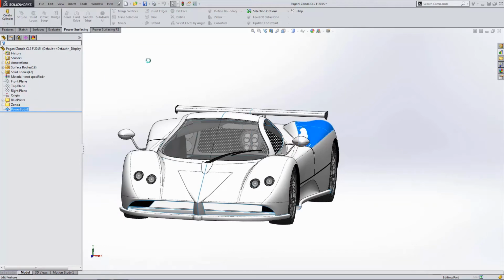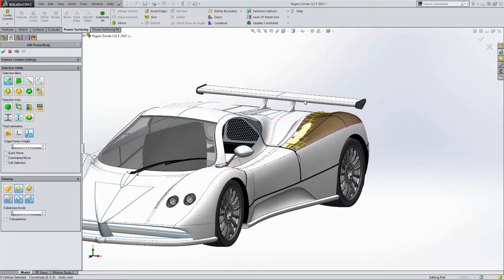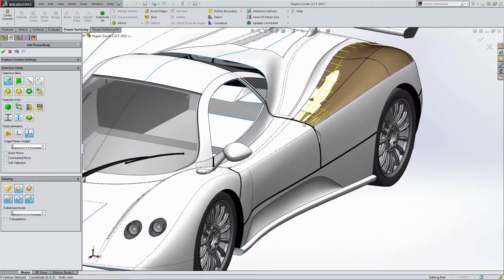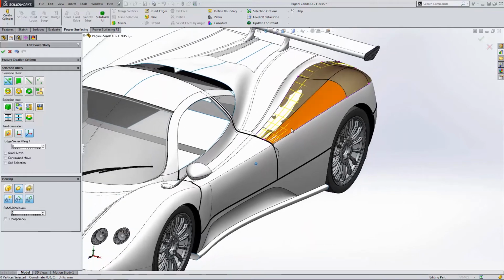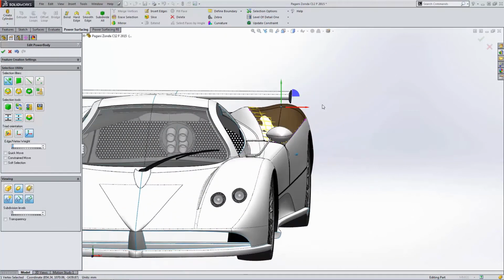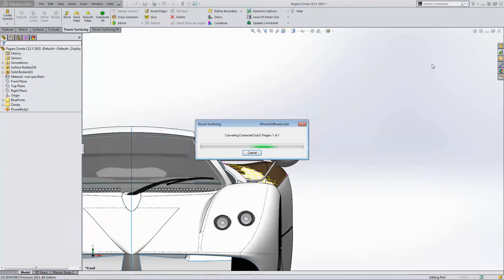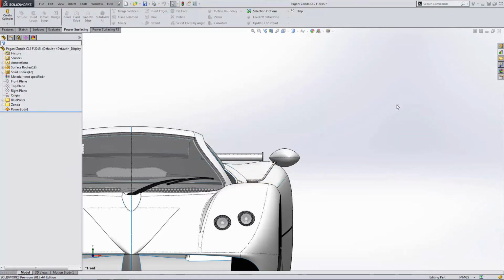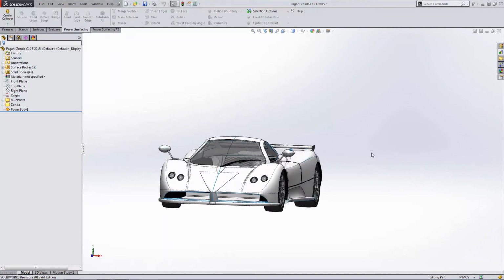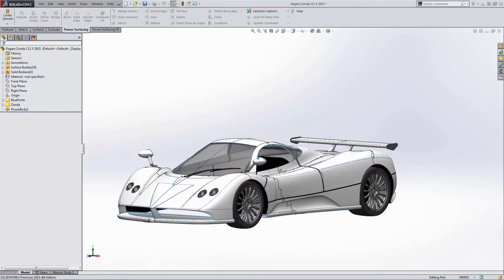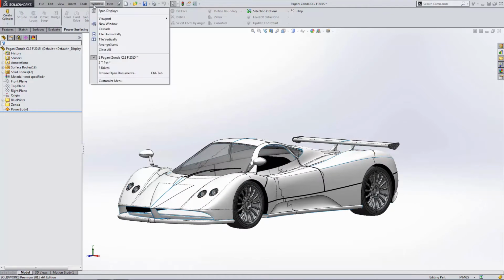Well, now with this new functionality of importing a reference, we can import a reference, create a planar surface, constrain its edge vertexes to the vertices on your imported reference, constrain the edges, and now what we have is a model where we have vertices, edges, faces that we can move around, create the shape we need, then use that to replace the face that we have on our original model. So this functionality alone gives you not only the freedom to manipulate and move, pull these in 3D, but to also not have to go through the painstaking process, going back through the feature tree, trying to recreate and readjust that geometry. Now, I know that not all of us create cars in SolidWorks. Unfortunately, it's a complicated process, but there are lots of other models where this functionality can be good.